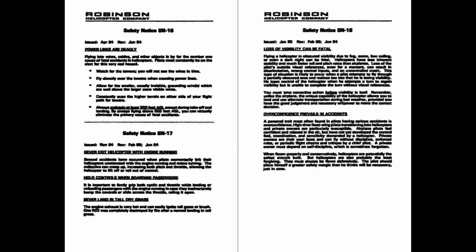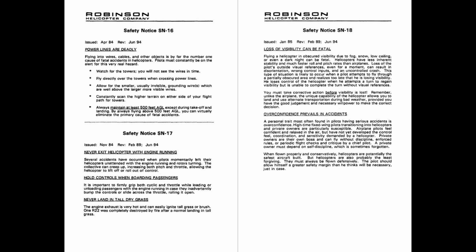Why should the pilot never leave the helicopter unattended while running? The collective can creep up, increasing both pitch and throttle, causing the helicopter to lift off or even roll.